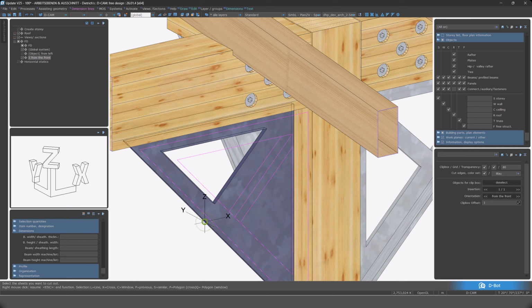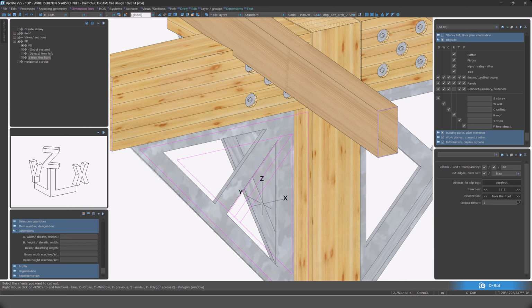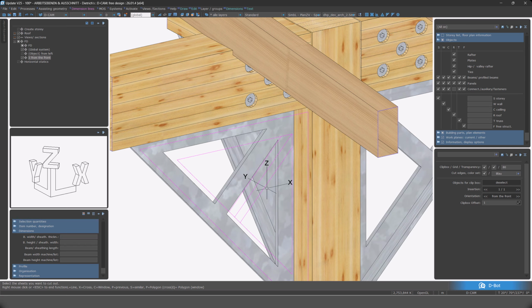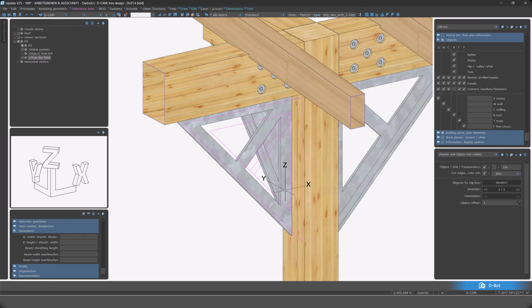I'm going to select that component again, right click, and now I'm in it. Now I can choose this point, that point. And to go down here, right click, and that closes the line. And there we go. That created the notches inside of this component. Okay, so that was a way for us to create these notches into this bracket.